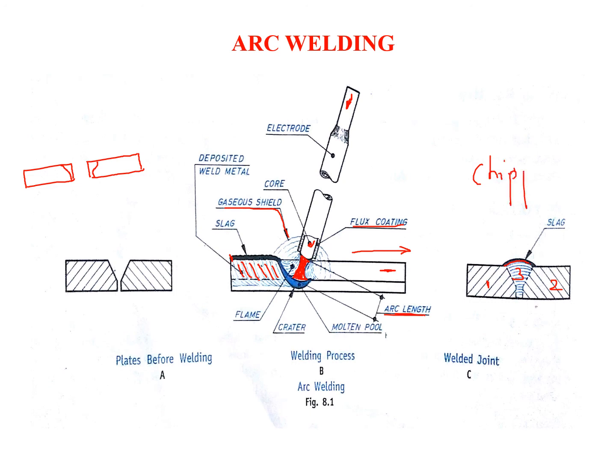We have something called a chipping hammer. With the chipping hammer we chip off the slag, and if we want we can also machine it. Then you will form a single component, and you will not even understand that these two metal pieces are joined together. Whatever slag was here has been removed. So this is called the arc welding method. Thank you.